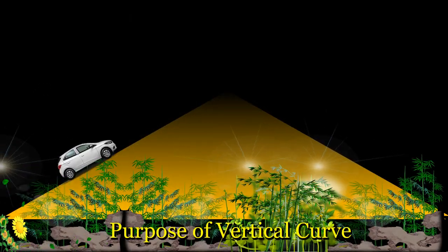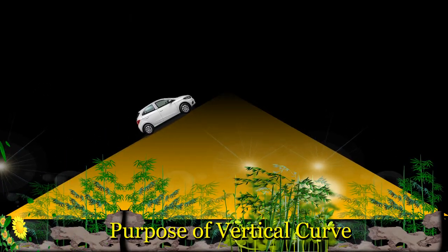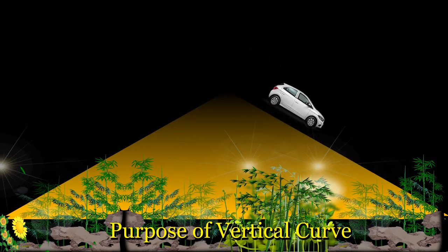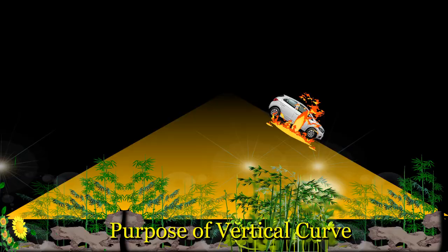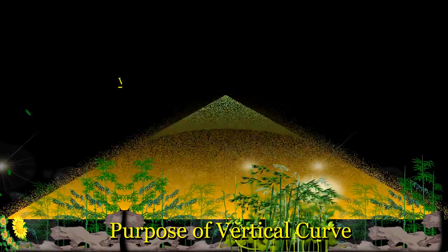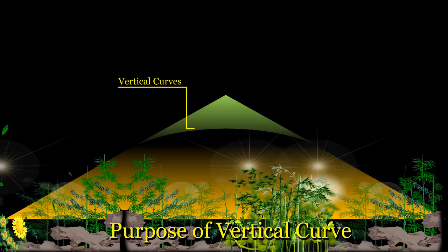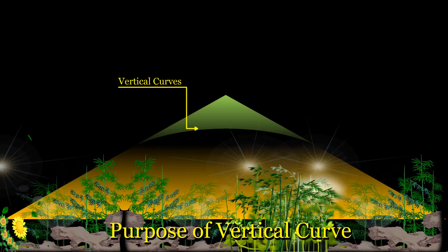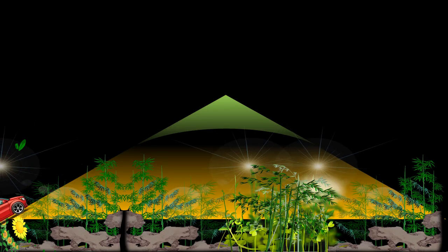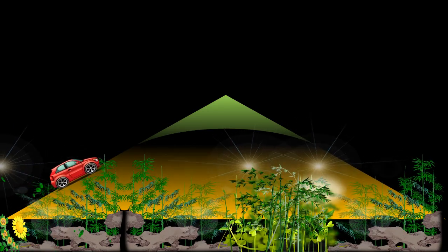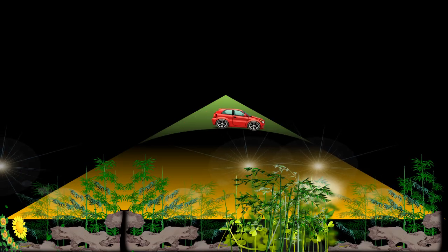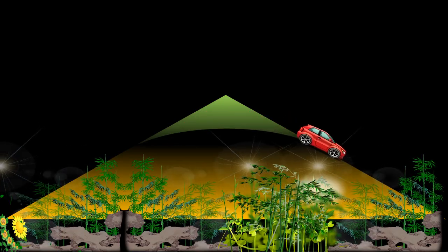On highways, abrupt changes in vertical alignment can create significant discomfort and even safety hazards for vehicles. Such sudden shifts in elevation may lead to accidents or vehicle damage. To prevent this, vertical curves are introduced to provide a smooth transition between two intersecting road grades. These curves ensure that vehicles experience a gradual shift in elevation rather than an abrupt change, enhancing safety, comfort, and overall roadway aesthetics.